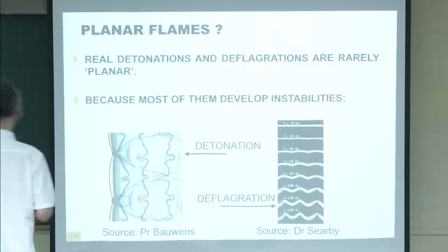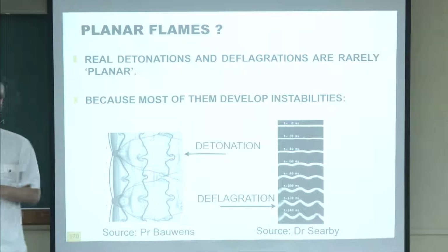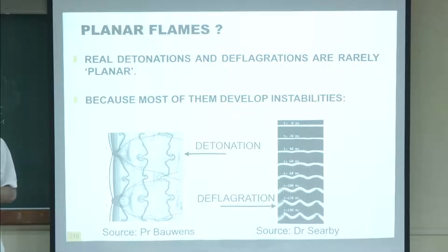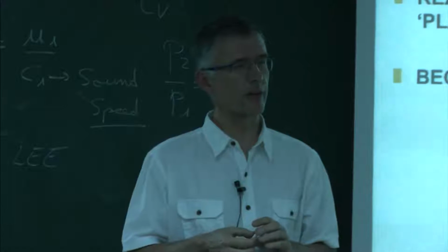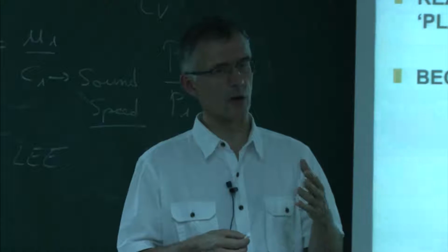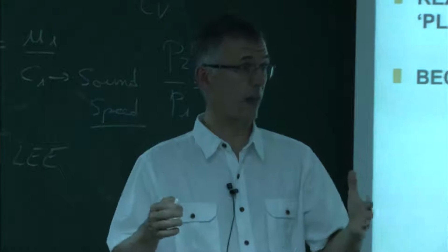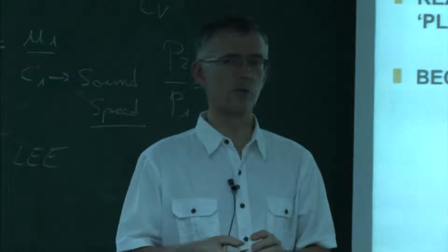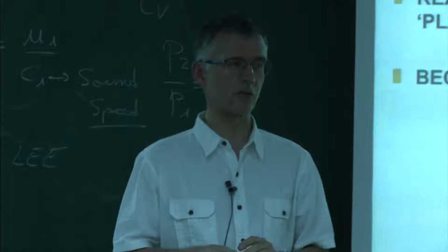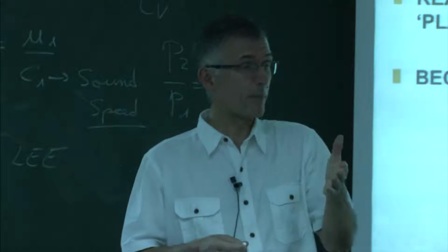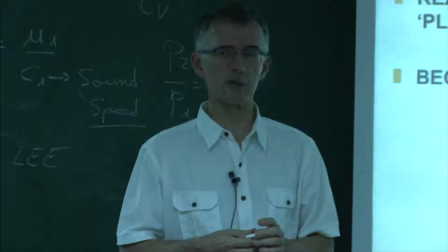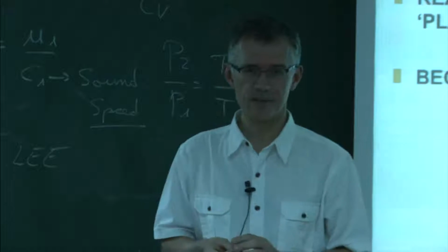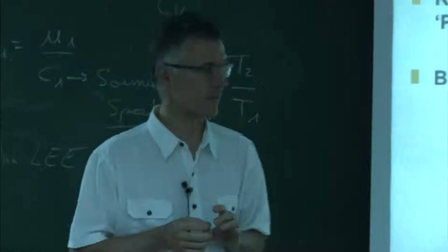No, well, not in a piston engine. In the rotating detonation engine, you could try to do that. But in a piston engine, if you would need to have an engine which does that, the weight would be crazy. Because a diesel engine, which resists 150 bars, is already a very heavy engine. So if you would need to go to 500 bars, it would be crazy. But you're right. On paper, it should have a very large efficiency. But the price would be crazy. No one's done it. No one that I know of, at least.